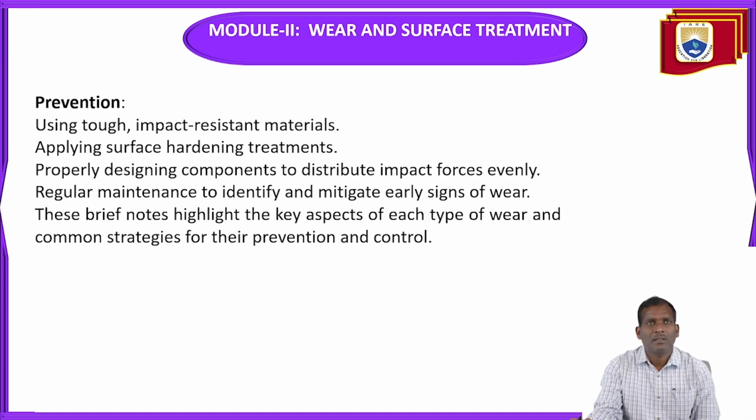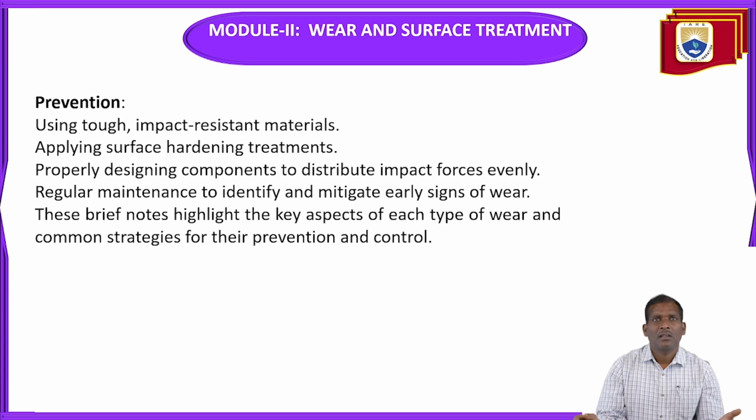Next, how to prevent? Using tough or impact resistant materials, so having material with high toughness and high strength to withstand the impacting. Applying surface hardening treatments like nitriding, carburizing, annealing. These all are surface hardening treatments. By using these hardening treatments, you can improve the life of the component, and also minimize the wear.